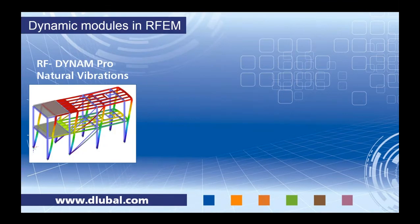So as I mentioned, we'll be utilizing the dynamic modules in RFEM. And we have 3 DYNAM Pro modules. The first one is RF-DYNAM Pro Natural Vibrations. This is essentially always needed. This will perform your natural frequencies and mode shapes for any members, surfaces, and solids in your model.